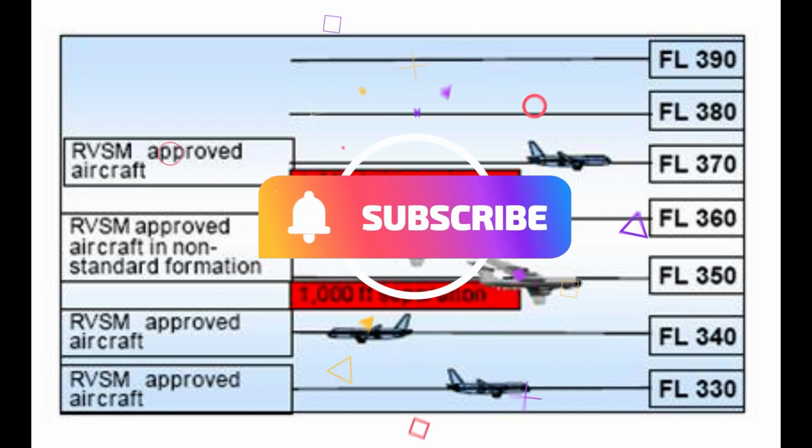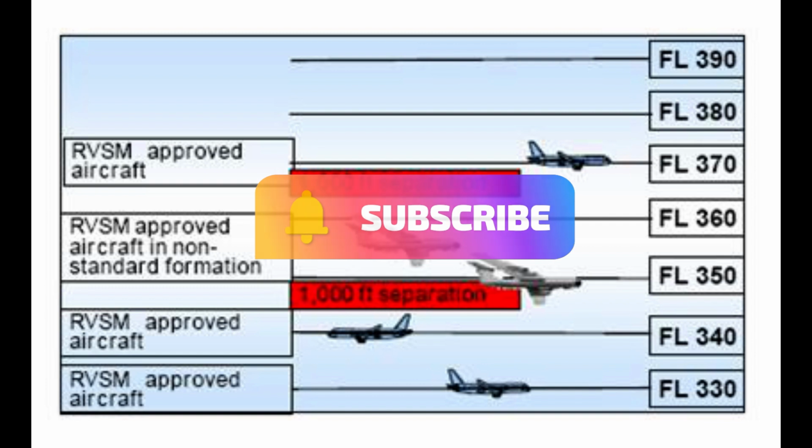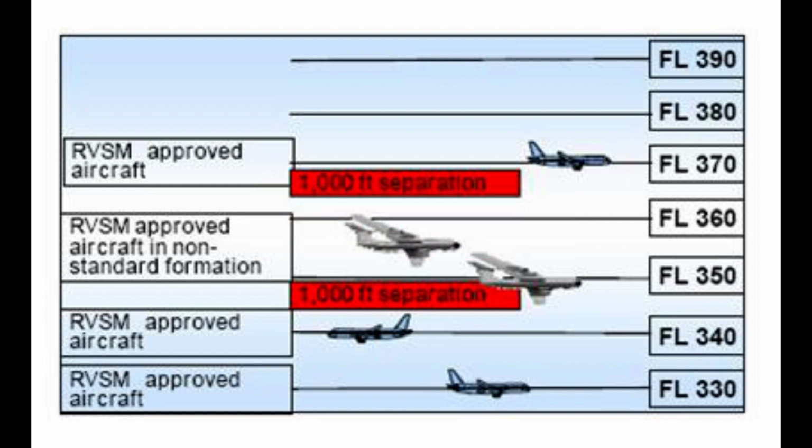Non-RVSM-approved aircraft may transit through RVSM airspace provided they are given continuous climb throughout the designated airspace, and 2,000 feet vertical separation is provided at all times between the non-RVSM flight and all others for the duration of the climb/descent. Critics of the change were concerned that, by reducing the space between aircraft, RVSM may increase the number of mid-air collisions and conflicts. In the 10 years since RVSM was first implemented, not one collision has been attributed to RVSM. In the United States, this program was known as the Domestic Reduced Vertical Separation Minimum, DRVSM.